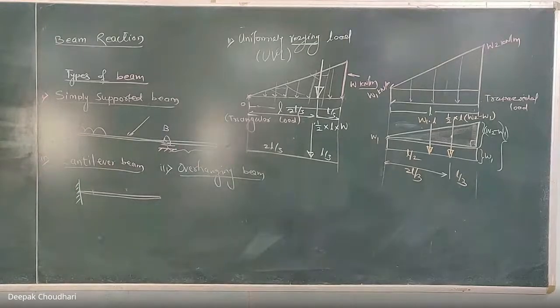Here, understood? These three types of beams are important from your subject point of view. Here, most of the time, 99% time आपको figure दिया रहेगा. उससे first step you have to draw the FBD. Here and then apply the conditions of equilibrium. Here, beam के reaction में जो force system बनेगा, that will always a general force system. So you have to apply the three conditions of equilibrium, and by using the three conditions of equilibrium, you can find at the most three unknowns.